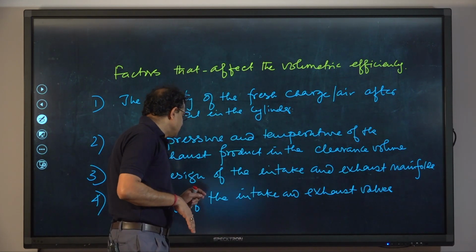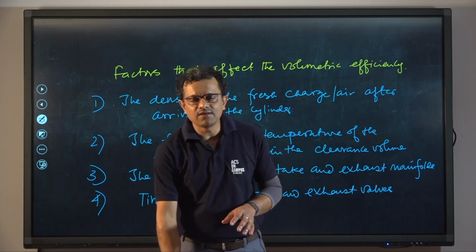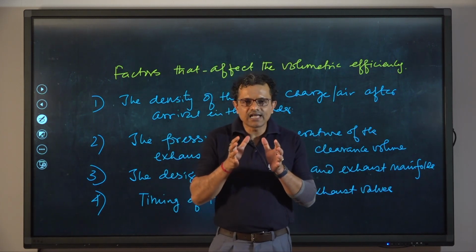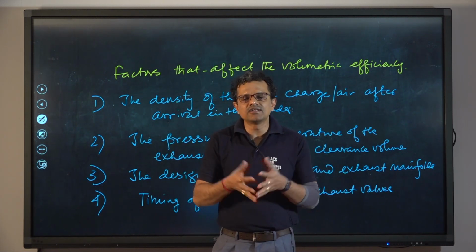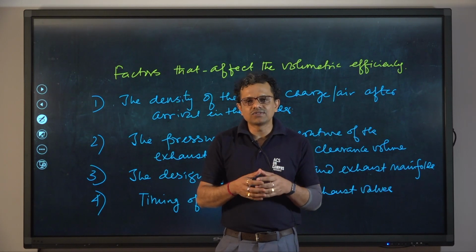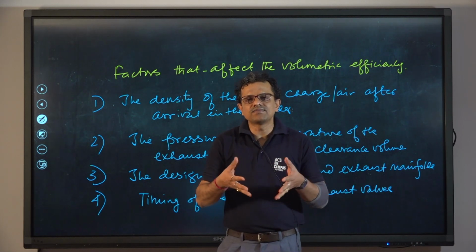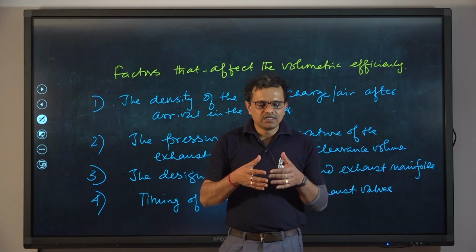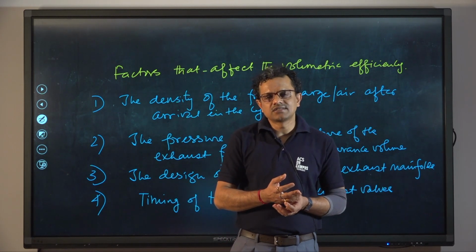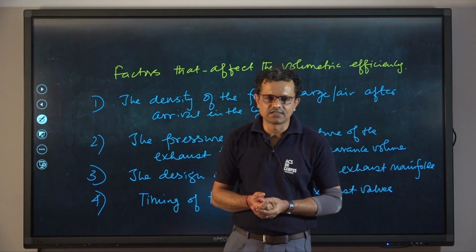Now, the timing of the intake and exhaust valves is also very important. If the intake valve opening and closing is done properly, certainly the actual mass needed to burn the fuel can be drawn in. Similarly, exhaust valves should open and close in time so as to allow combustion gases to escape from the engine cylinder in time, otherwise they will dilute the fresh charge drawn into the engine cylinder during the intake stroke, which in turn will reduce the volumetric efficiency.